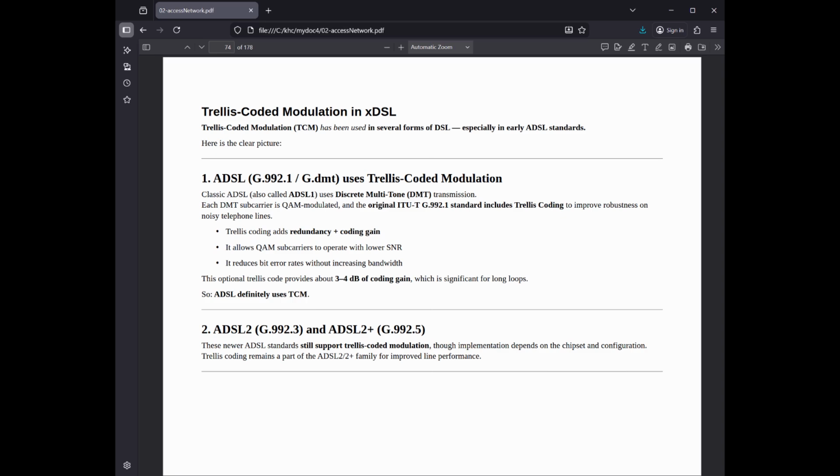TCM and the dual bitmap. The Japan case. One unique application of TCM in the DSL world occurs in environments with TCM-ISDN interference, common in Japan. Because ISDN lines there use a specific timed burst, time compression multiplexing, they create noisy and quiet periods for nearby DSL lines. xDSL systems use TCM-aware synchronization to switch between 2 different bit loading maps, dual bit maps, to perfectly time their transmissions with the quiet periods of the interfering ISDN line.